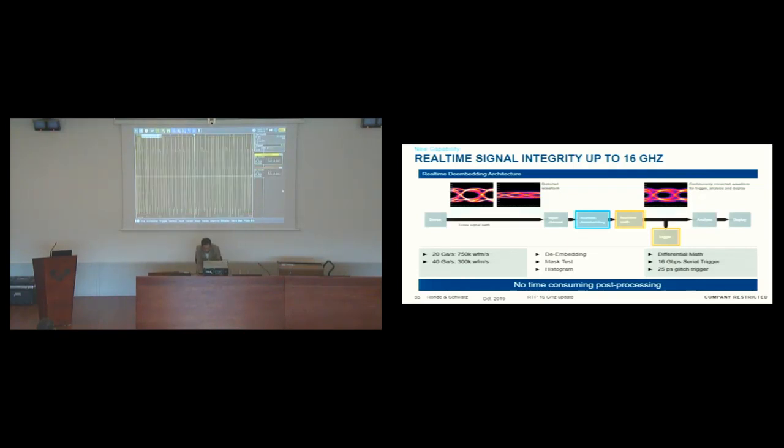Now, channel 3. We'll do differential, 100 millivolts per division. Now we have our clock, our signal. Now we are going to trigger on this differential signal.